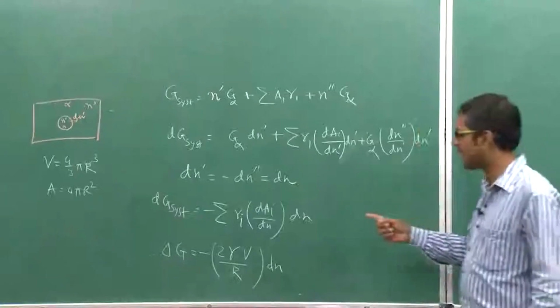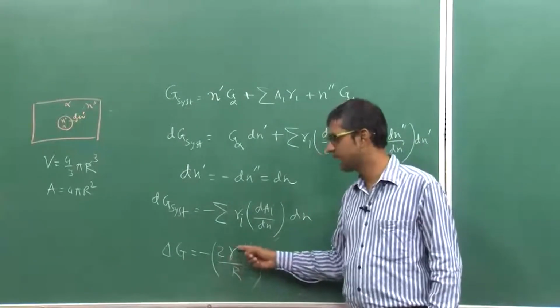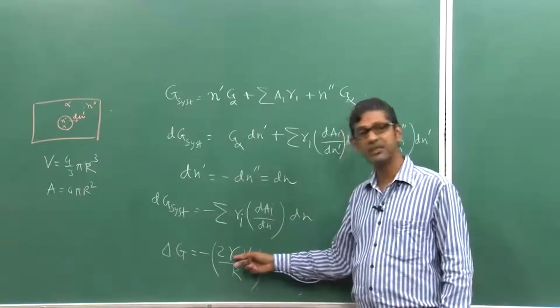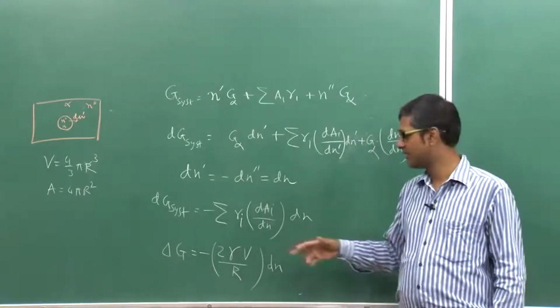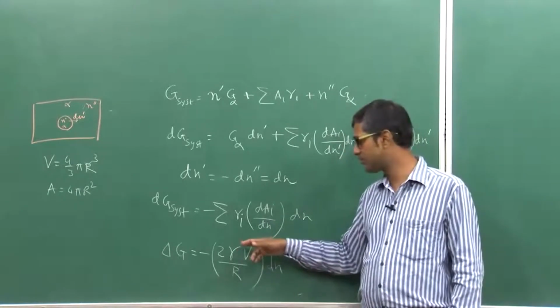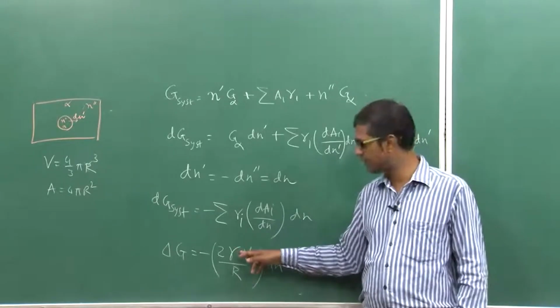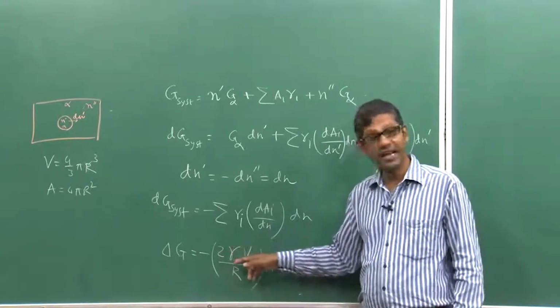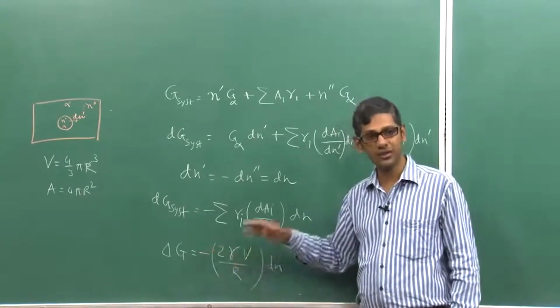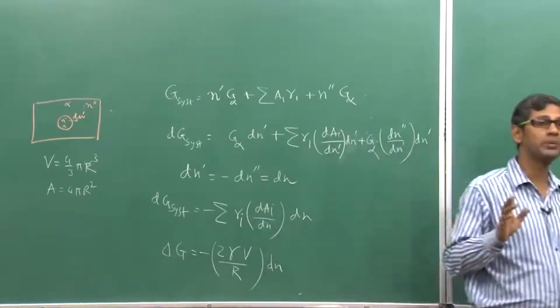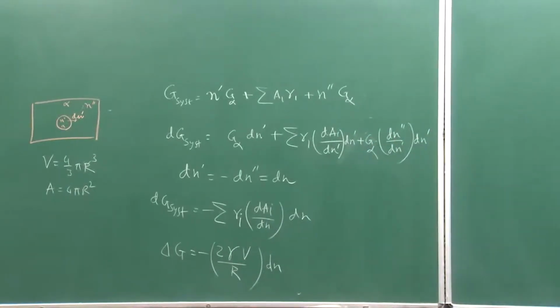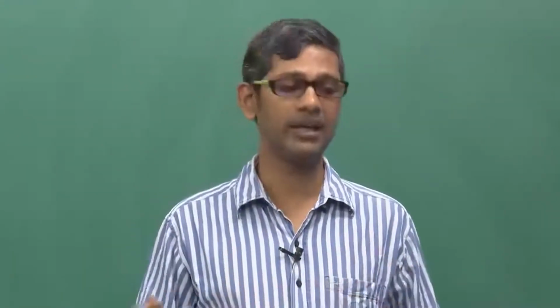Gamma depends on many things: the crystallographic orientation, and the double derivatives of gamma with respect to crystallographic orientations, by which we can actually change the sign. There are such situations, but let us not get into those complex cases. This happens when you have special grain boundaries. But normally, for normal grain boundaries, whatever I said will be valid.